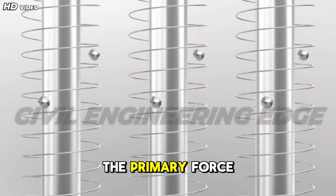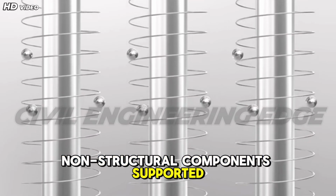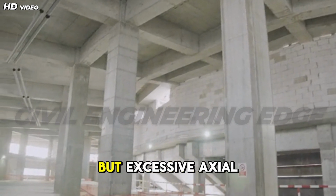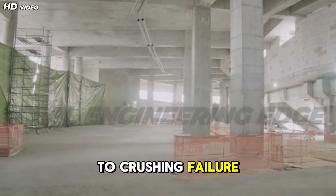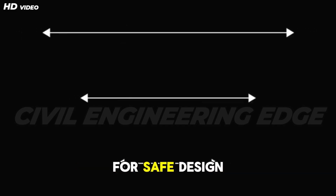Axial load is the primary force acting on a column and results from the weight of structural and non-structural components supported by the column. Axial compression reduces the effective tensile stresses in concrete, but excessive axial load can lead to crushing failure. Accurate calculation of axial load using proper load combinations is essential for safe design.